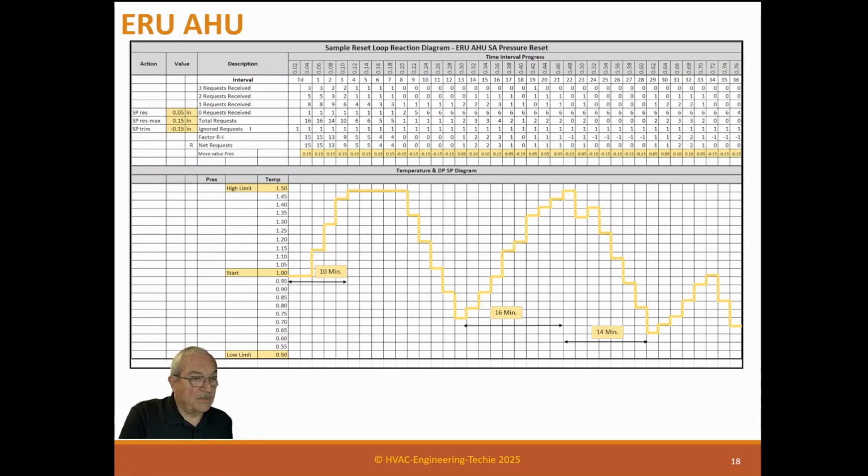And a half hour is a good rule of thumb of where to be under. What happens is, over a half hour, people can realize what's going on. Because if you couldn't catch this, you wouldn't be able to change building pressure. And when the building pressure gets negative for a long period of time, people will notice, and it'll start bringing in debris. So basically, I always use a half hour for these intervals.